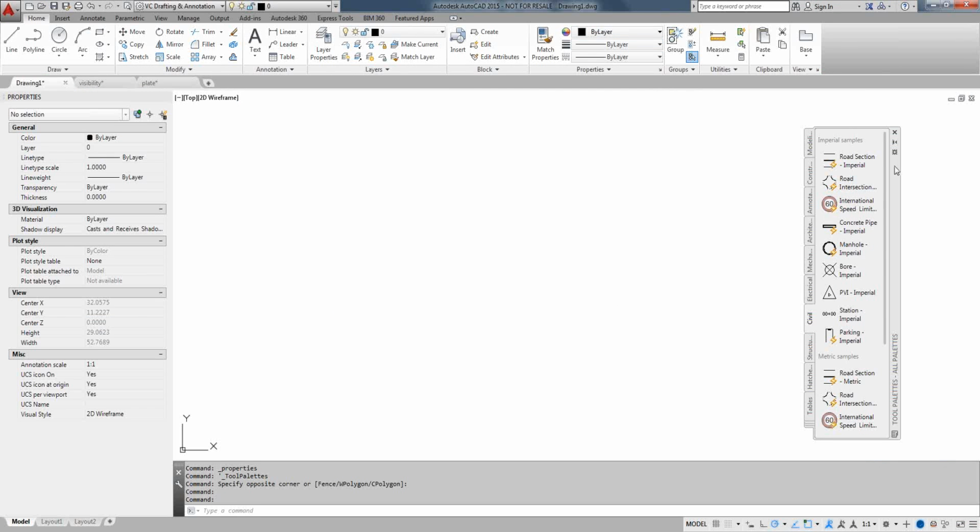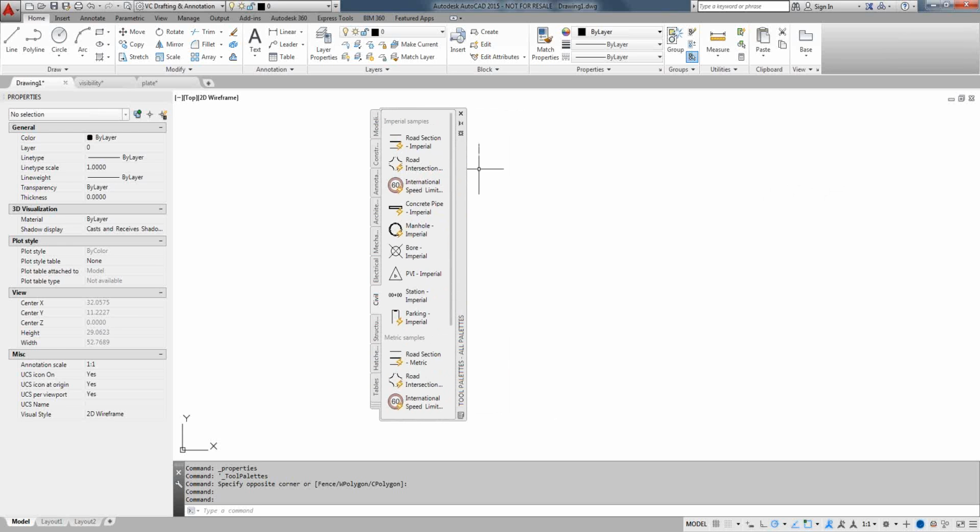So you're probably very familiar with this particular palette. It's the tool palette. And AutoCAD has several dynamic blocks available as a sample. I'll discuss this palette after my initial demo of how to create blocks. But what I wanted to show you right away is that you can easily tell which is a dynamic block just because it puts this little lightning bolt symbol next to that block. So if you see it in a palette or in the insert command or anywhere else next to a block, that shows it's dynamic, as opposed to the static blocks, which do not have that symbology.